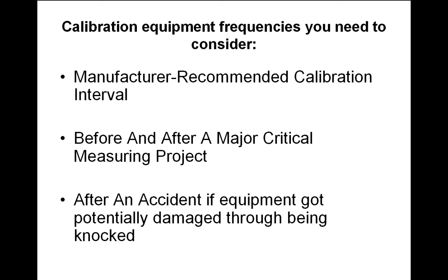We were measuring two 24-volt power supplies, and one had a voltage of 24.1, and the other had like 24.2 volts. So they were slightly out, but you could calibrate the power supply itself. Meter calibration is a different story, but you can at least verify that the meter is within range, like 1 or 2%.